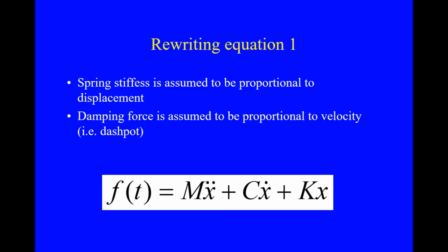And for a long time, that caused us all sorts of problems, particularly between wind and earthquake engineers, because damping is different at different amplitudes. If you assume that it ought to be the same, then you've got different values to use for wind engineering and for earthquake engineering. And of course, the two groups will face each other off and say, you just don't understand what we do.